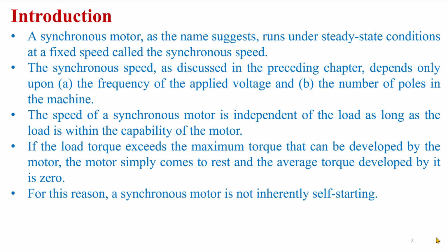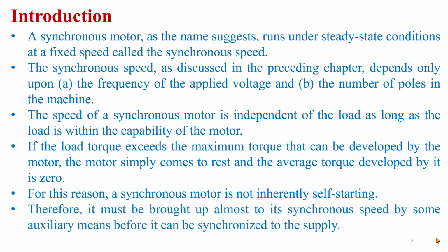Okay. So for this reason, a synchronous motor is not inherently self-starting. So it cannot self-start. Why it is not self-starting, I will explain, because there are some issues. So it is unable to start by itself. As soon as you connect the supply to the synchronous motor, it cannot start unless we take it to a speed near the synchronous speed. So therefore certain arrangements are made.